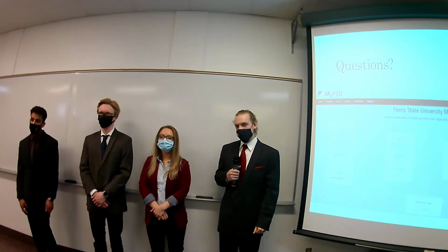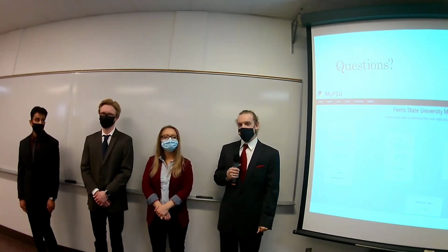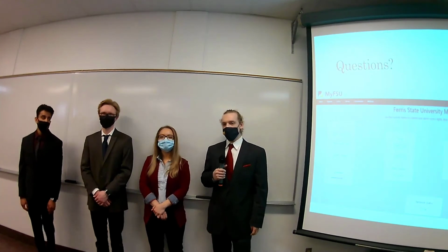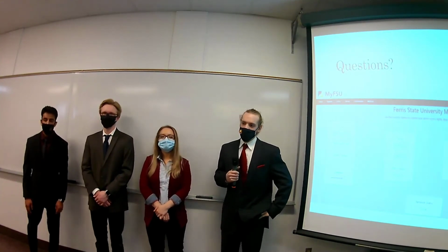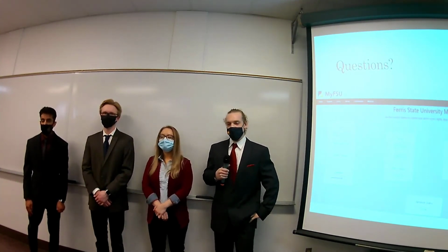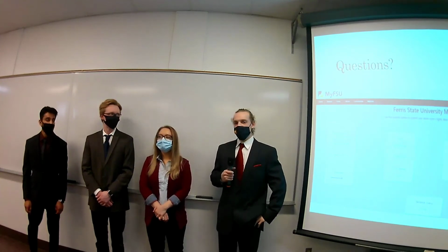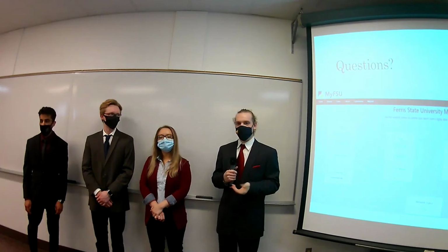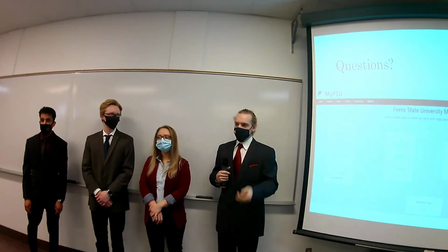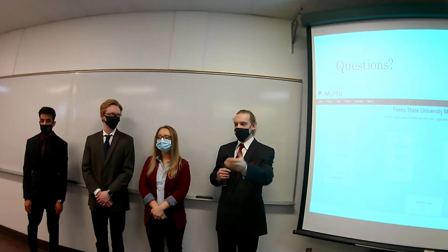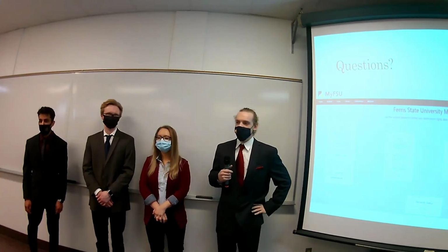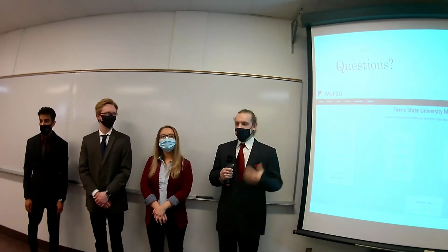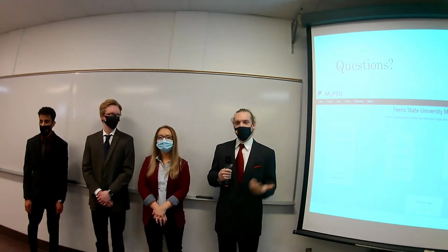Do you think there could have been better options? Most certainly, yes. There were infrared sensors out there that we had considered. Granted, we considered them too late, because we had problems with interference with the ultrasonic sensor, since it uses sound. Once in a while, it would open up the window on its own or something like that. But by the time we got to testing it, it was too late to implement something else.